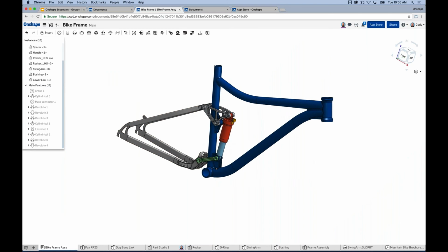Two questions that I missed, forgive me. Is it possible to edit an IGES or STEP file? Remember, an IGES and STEP file don't have sketches or features, so you won't be able to edit the sketches or features, if that's your question. You can do direct editing, commands like delete face, move face, resizing fillets. But remember that an IGES or STEP do not have the sketches or features, if that's what you're trying to edit.